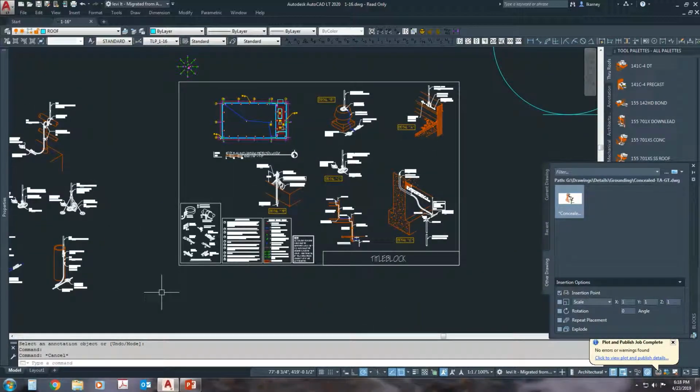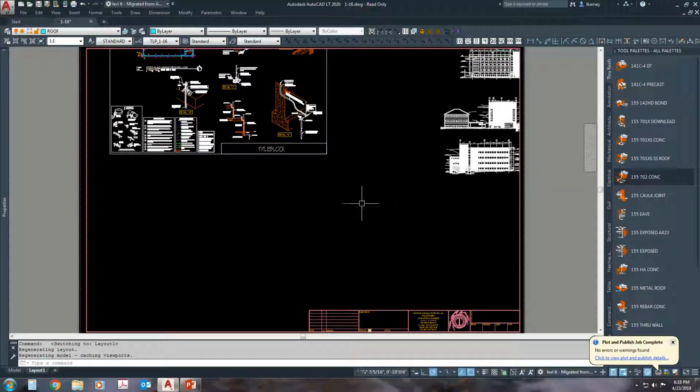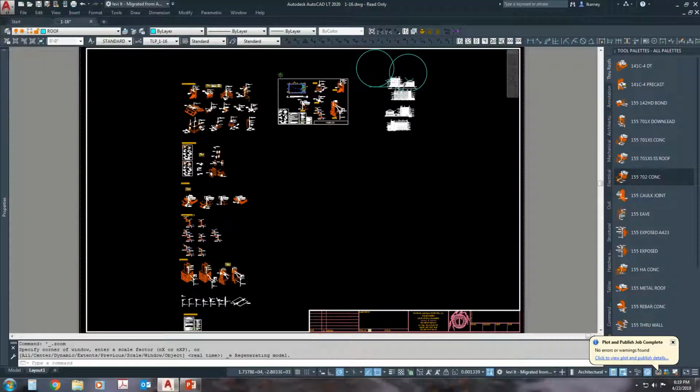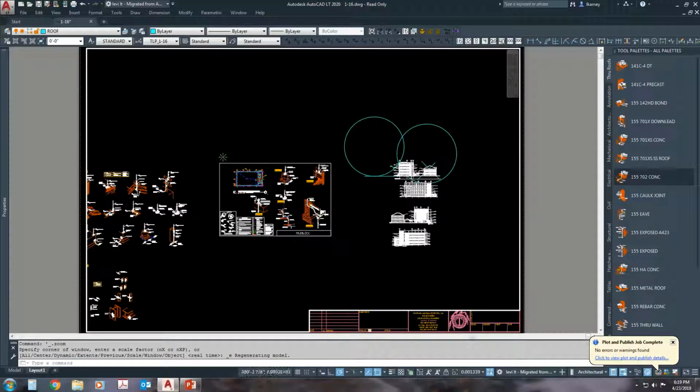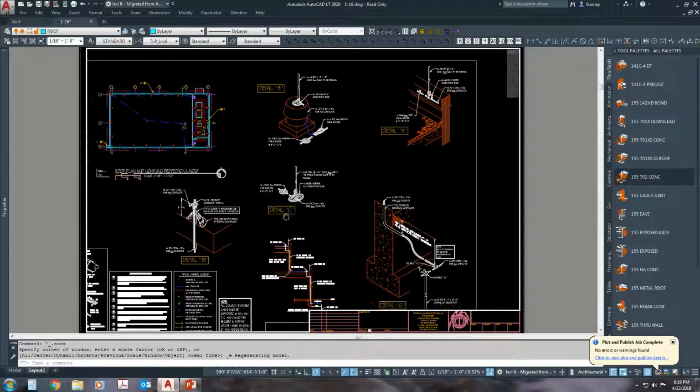And last but not least, what we end up doing is filling out the title block with the project name, and there you have it. Your layout is done. I will essentially take this, PDF create it, utilizing the PDF creator that's already built into AutoCAD, and you will have a finished lightning protection drawing.